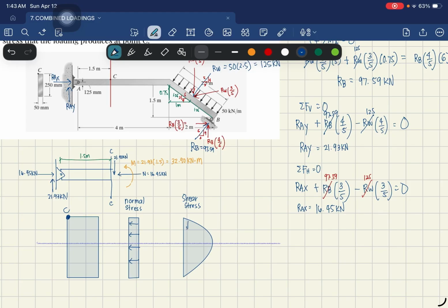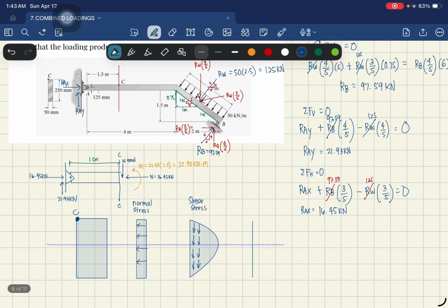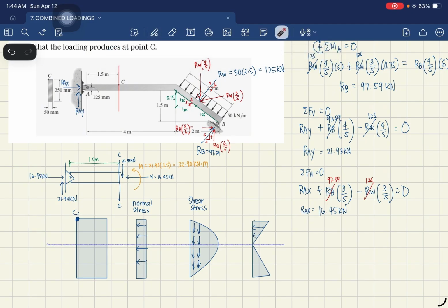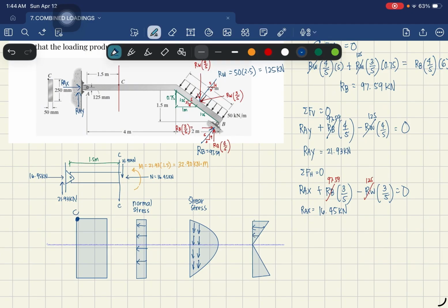Then, yung behavior ng shear, para mag-slide siya pababa. So, yan yung shear natin. Then, for the moment or bending stress naman, kabaliktaran siya ng shear. So, yung outer or uppermost at saka lower part ng cross-section, nandun makikita ang maximum bending stress. Kung saan yung upper fiber ng neutral axis is compression yung nararanasan. Ito naman yung bending stress.